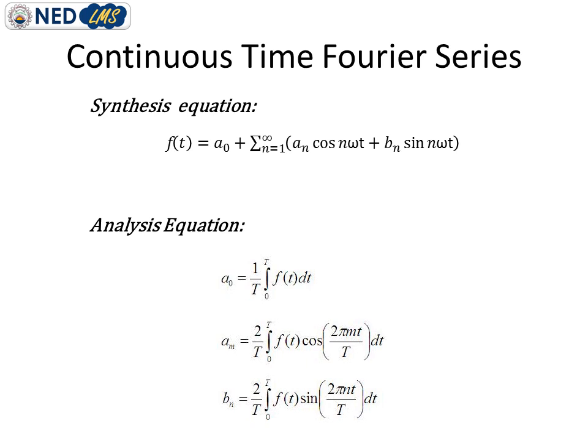As we are interested in determining the individual components, we are dealing with the analysis equation. We have to put our focus on the analysis equation rather than the synthesis equation, because we want to explore the building blocks, the number of sinusoids, the nature of sinusoids, or the number of spectral components and their quantities in any complicated waveform.